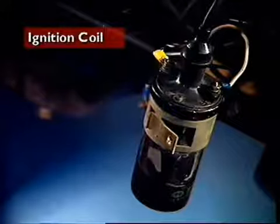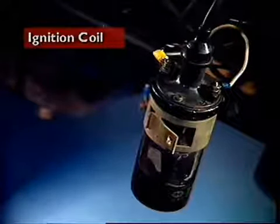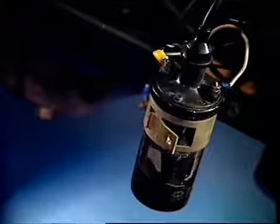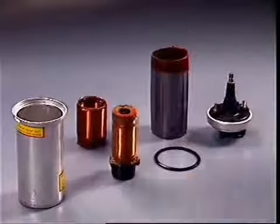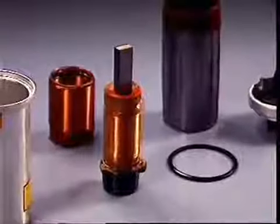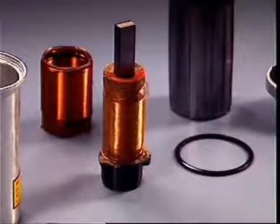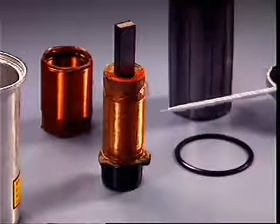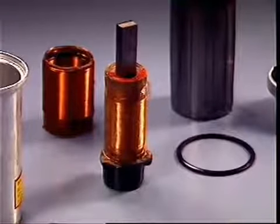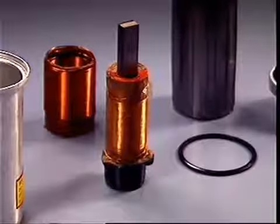The ignition coil is a step-up transformer which raises the nominal battery voltage of 12 volts up to the many thousands of volts necessary to provide a spark across the spark plug electrodes. A standard ignition coil has a rod-shaped laminated iron core which is located centrally by an insulator at its base. The secondary winding with 15,000 to 30,000 turns of very thin enameled copper wire is wound around the core and is insulated from the core by layers of treated insulated paper.